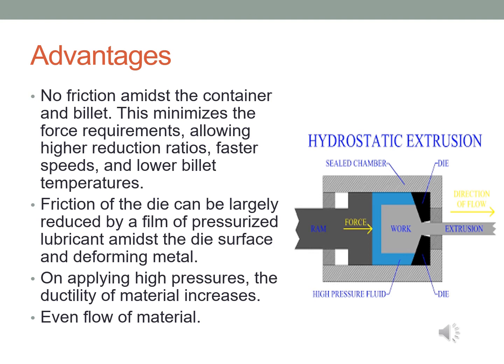What are the advantages? There is no friction between the container and billet. This minimizes the force requirements, allowing higher reduction ratios, faster speeds, and lower billet temperatures.